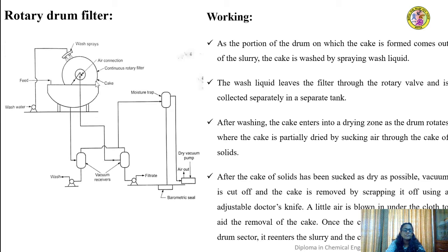Again, after the removal of the cake from the surface of the drum, that surface is now free of any solids. Again, when it dips into the slurry, it will suck additional filtrate along with the deposition of a fresh thickness of cake.